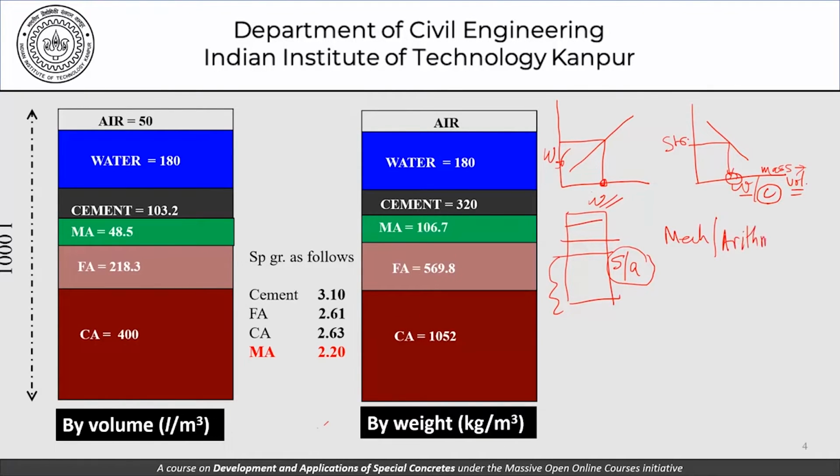The principles behind it we had revised, and it turned out that this was one of the approaches we can use to proportion a concrete mix, using primarily a volumetric balance using this 1000-liter pitcher. We use the story of the crow to say that as far as the pitcher is concerned, the absolute volume of all the constituents must total 1000 liters or a cubic meter.